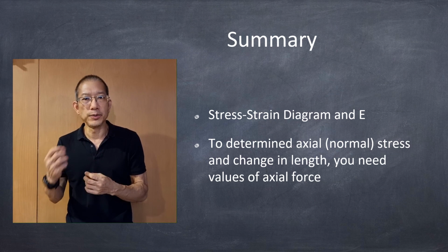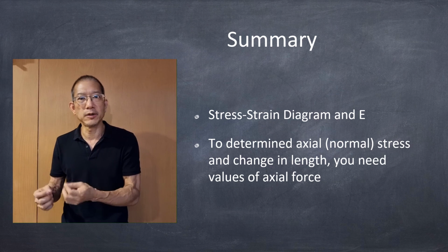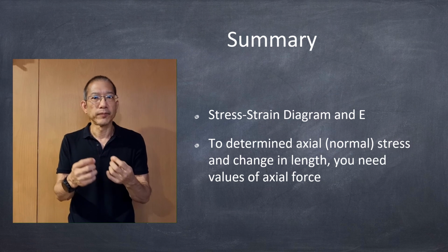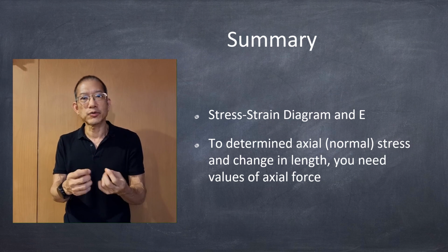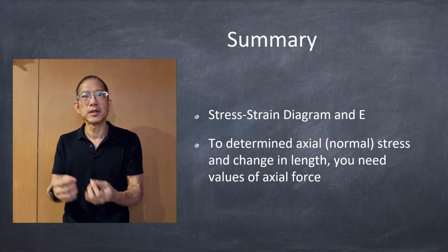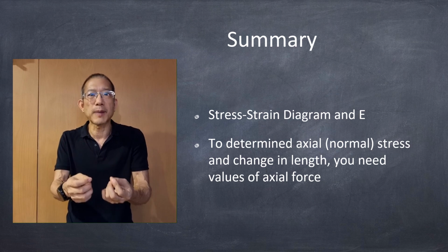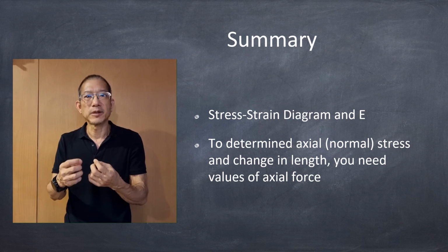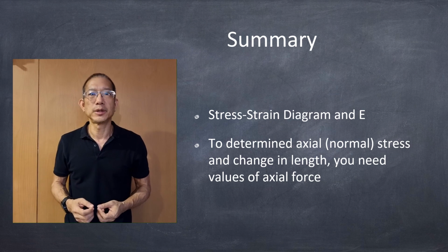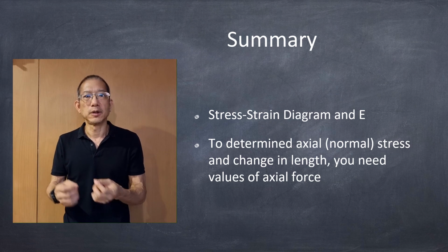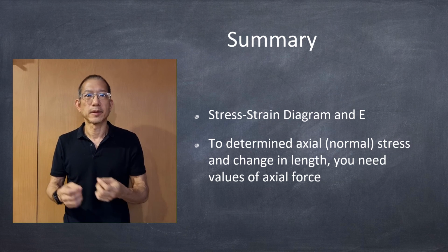But the value you need in calculation is always the internal force. The axial stress, sometimes called normal stress, and the change in length caused by axial force must be substituted into the equation using axial force, not external force.